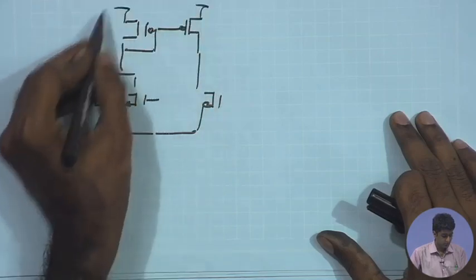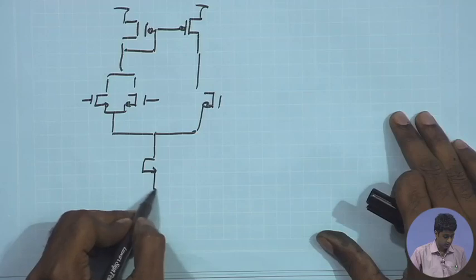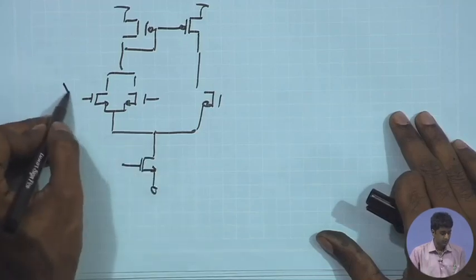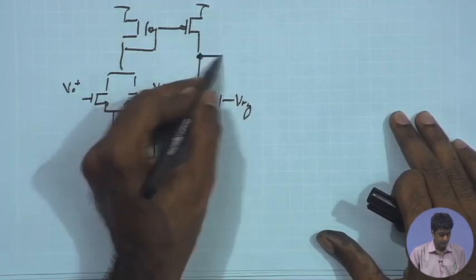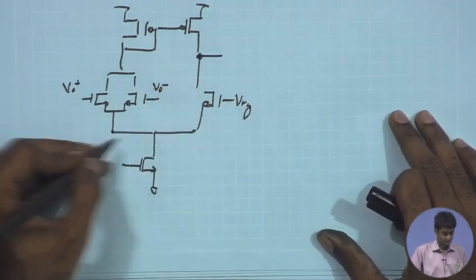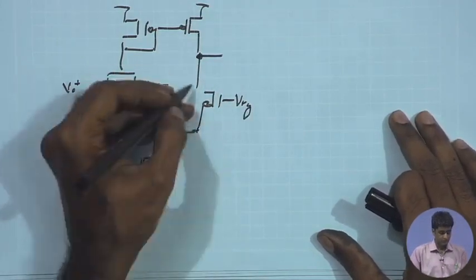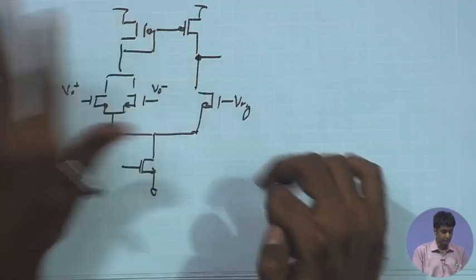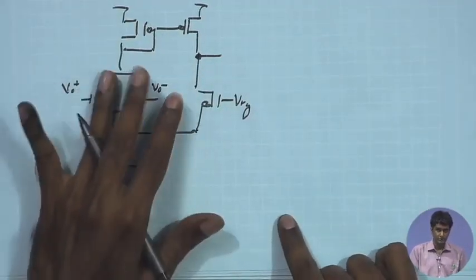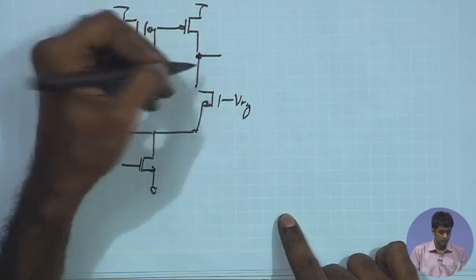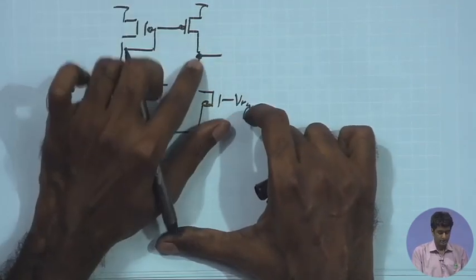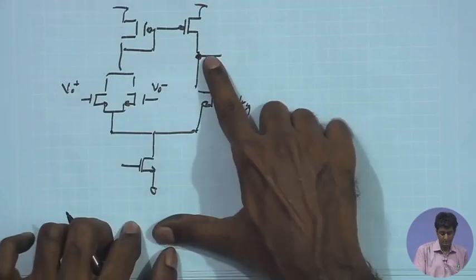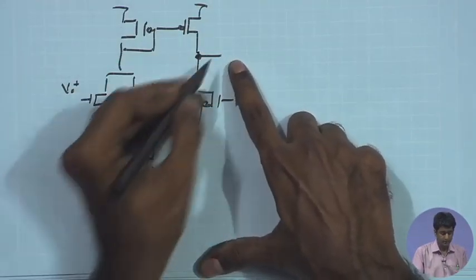dual loop common mode feedback where we are relying on the diode connected load, and this is your VO plus and VO minus coming, and this is your Vref. One of the important constraints would of course be the gain. We would like to have sufficient loop gain, so the GMRO product should be sufficient, and also we need a sufficiently large RO over here so that the compensation does work. Remember, for the common mode feedback, the compensation point is this one.